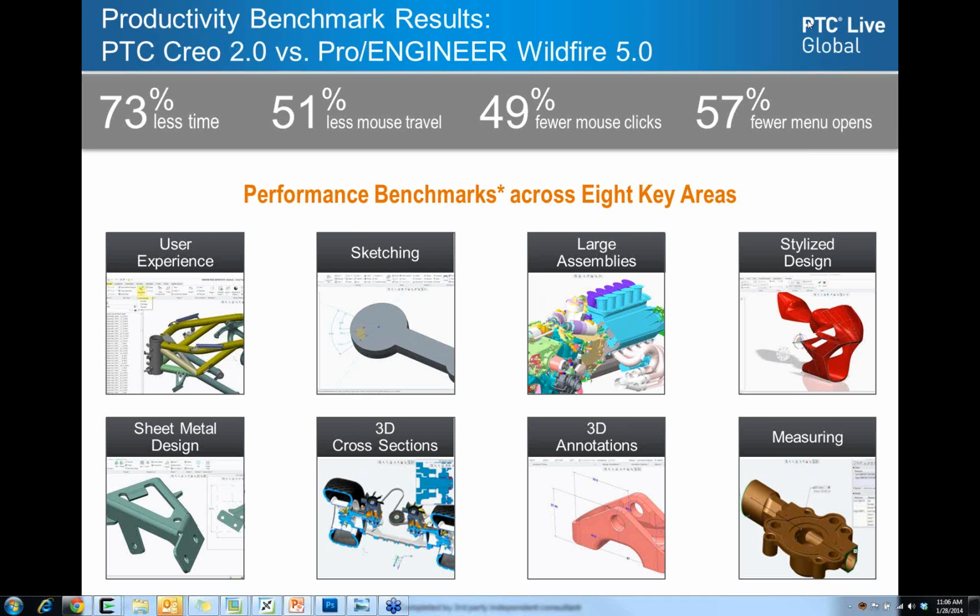We added a flattened preview window, so as you're designing your sheet metal parts, you can always see the flat state of your sheet metal component. Inside the flat state, we will also show interference checking. So if there's a problem when you flatten this sheet metal part, that it can't be flattened because it's going to have overlapping geometry, we will highlight that for you in the flat state.